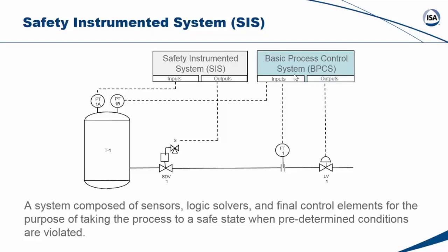But because the safety system is a passive or dormant system, not all failures are self-revealing. An isolation valve that's open all year round might be stuck. A pressure switch that only activates when pressure goes high, what if it's stuck and not responding? You will only know either when there's a demand and it doesn't work, which is not going to be good, or you have to periodically test these systems to be assured that they will work when you need them.